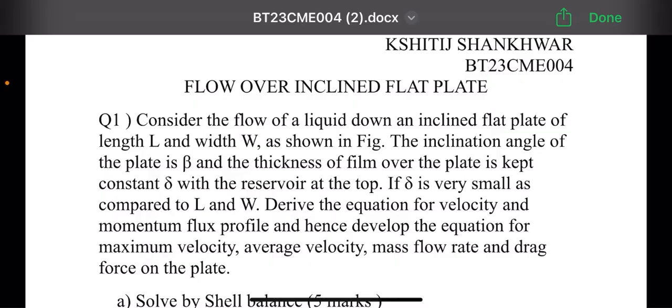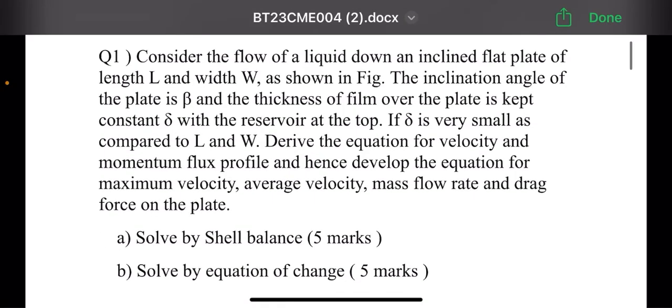If delta is very small compared to the length and width, derive the equation for the velocity and momentum flux profile, and hence develop the equation for maximum velocity, average velocity, mass flow rate and drag force on the plate. We will solve this question by two methods. First is shell balance and second is equation of change.